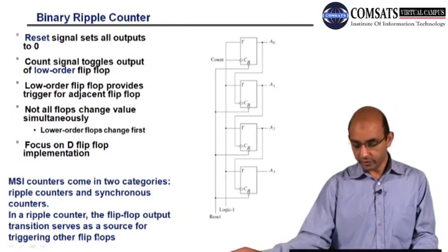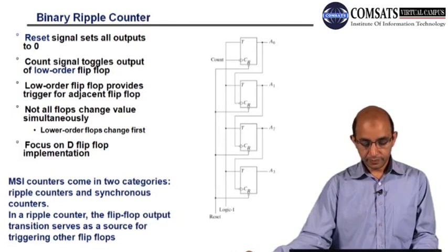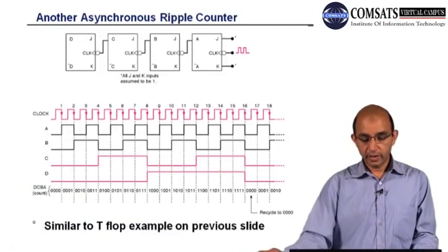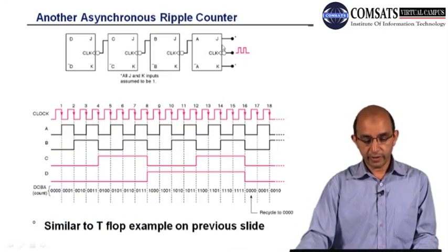Now we are going to discuss the ripple counters where we have used JK flip-flops. You can see this is the clock, and this is the output of this flip-flop, and that has been provided as the input over this clock signal. And we can think about this bubble. It means this is active low, so the falling edge. The JK flip-flop will trigger on the falling edge.